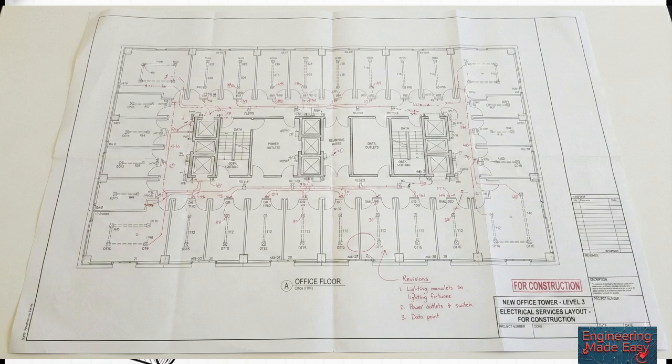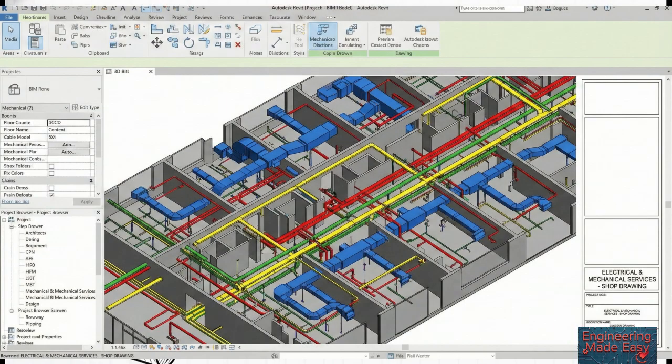And these shop drawings are absolutely critical. They're the missing link that translates the engineer's what and why into the contractor's how and where. They're used to resolve any clashes between, say, our conduits and some mechanical ductwork. They detail how things will be mounted and supported, and they confirm the exact dimensions of the equipment being installed. Basically, they make sure everything fits and can be put in place correctly and efficiently on a real-world job site.